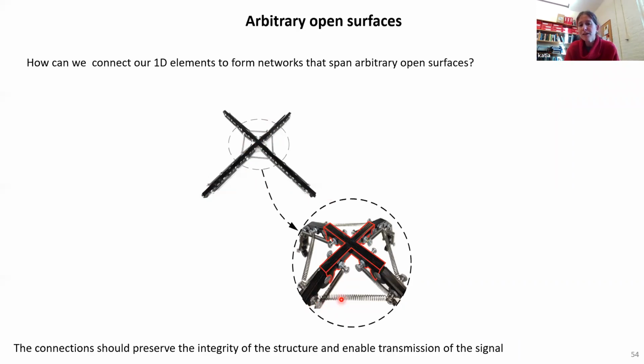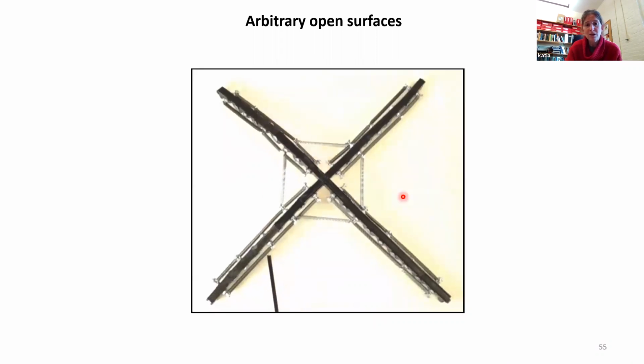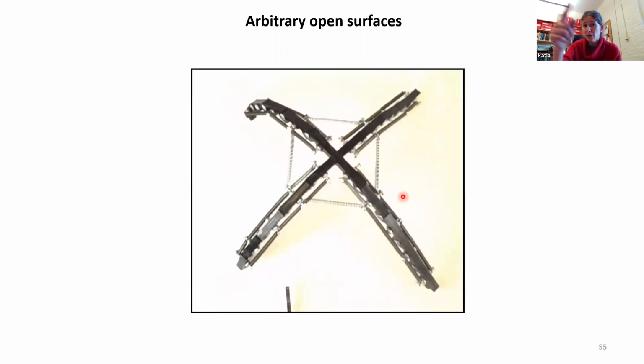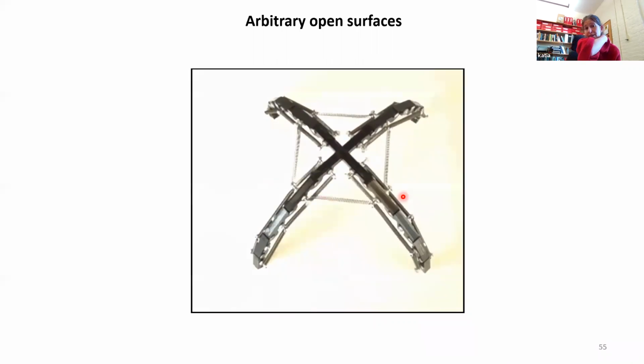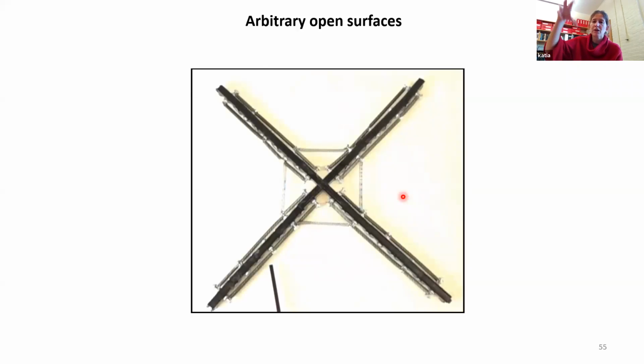To enable this, what we did is basically add this additional spring here. The role of these additional springs is to make sure that the signal propagates, to basically elastically couple the 4 legs. And here is a simple experiment. Now we have 4 legs connected by a rigid cross and 4 springs. We keep one end and we see one end snap to the curved configuration. Then we see the 3 other legs follow. So we started flat and now we have a dome configuration. And the structure is clearly stable also in the expanded configuration because it's a multi-stable structure.